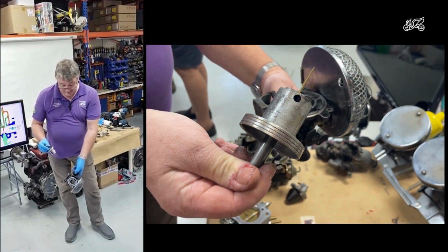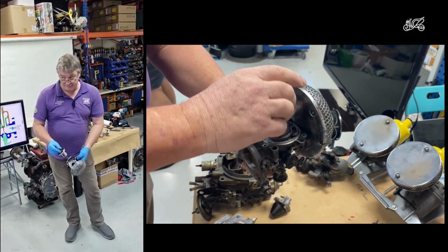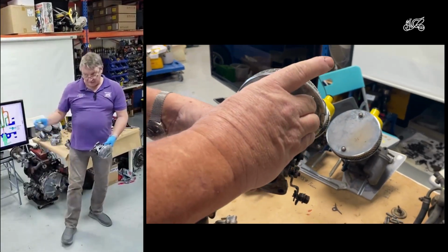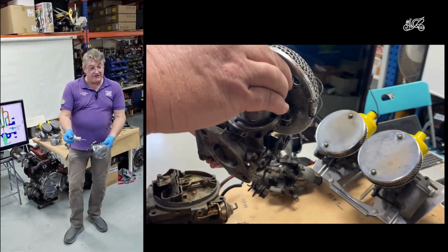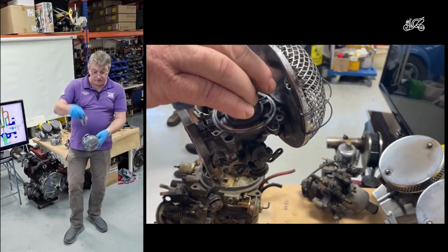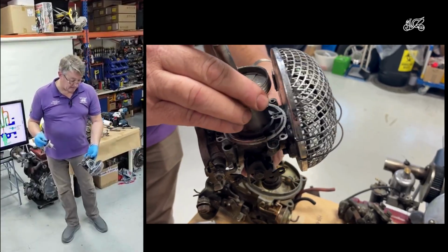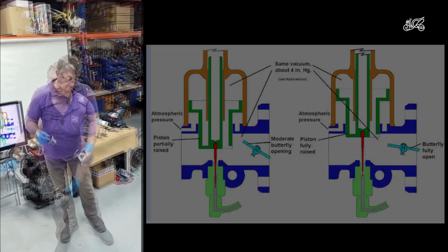Because the jet is so big, they're also quite resistant to bad fuel because it will come out the jet. Okay, it goes into your engine, which is not so good, but it won't block the jet because the jet is a big thing and the jet's got a moving needle in it, and so it can clear itself quite easily. It's just a piston and a jet.